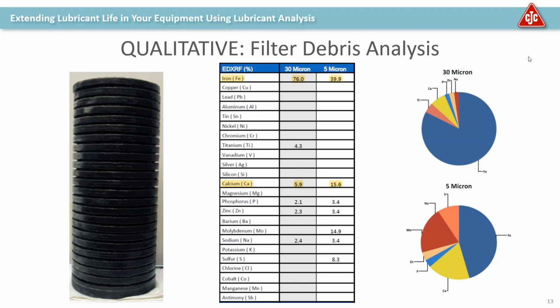And that's interesting about filter debris analysis, because just a quick story, something that I've run into a number of times is someone, probably similar to your person, will know that there's something wrong. There is some sort of issue. And they'll send in an oil sample, everything looks good, it comes back normal. There's no evidence in the data for me to tell my customer that I can definitively tell something's wrong. But I will often ask that they send in a filter for filter debris analysis,